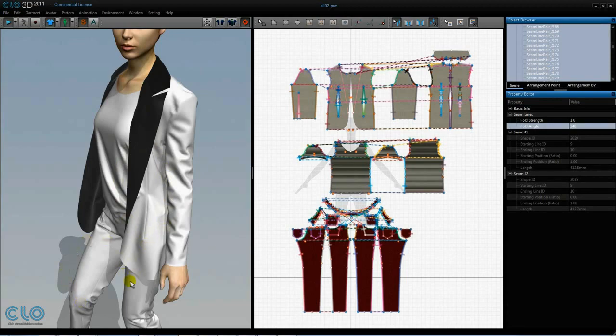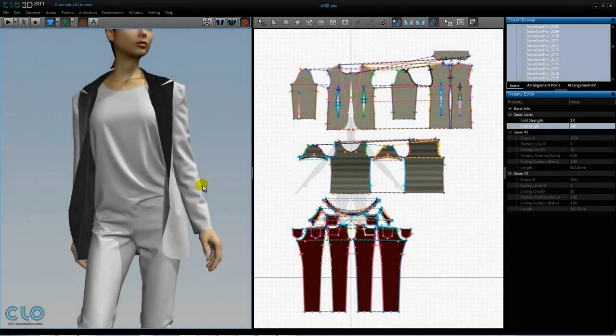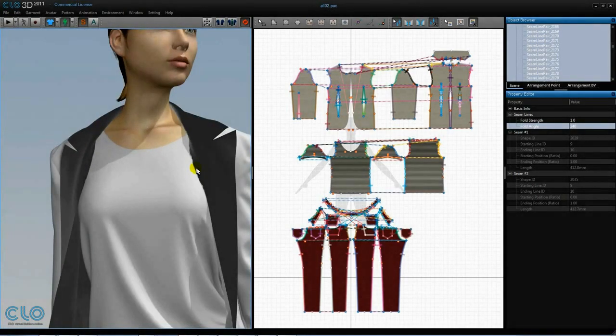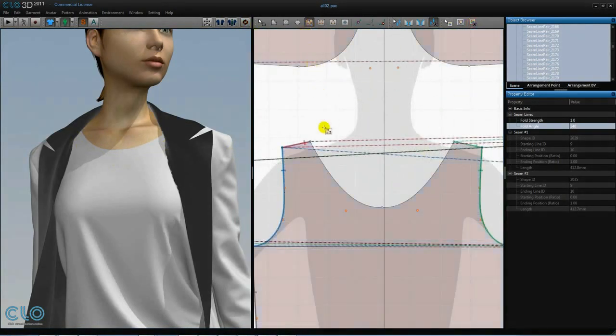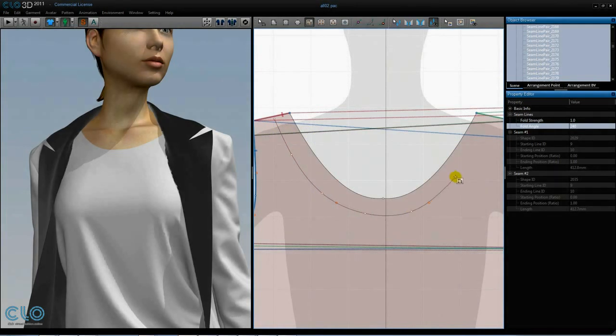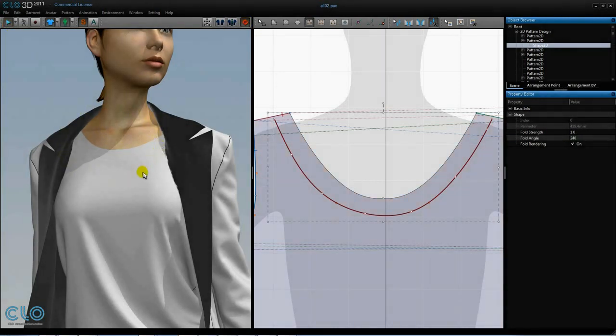You can use the same technique to express top stitching, but instead of adjusting the angle for seamline pairs, you adjust the fold angle of internal lines. For example, for this t-shirt, we can use the internal polygon tool to draw a top stitch line, and then change the fold angle to a value between 220 and 240 degrees in the Property Editor. Sync and then simulate, and the lines fold in just a little bit to give the effect of a top stitch.